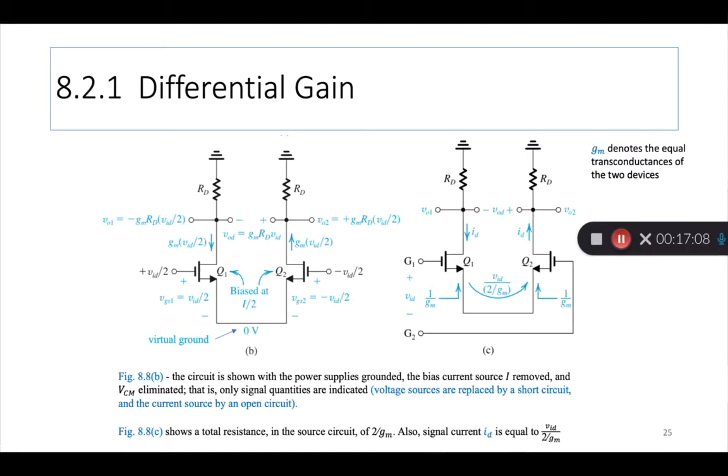So make sure you follow that logic there. The signal voltage is the source. A plus is applied here and a minus is applied here. And that is driving a current through the two transistors and through the load resistance that is applied somewhere here between the two. Okay.